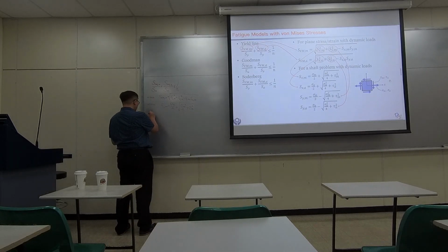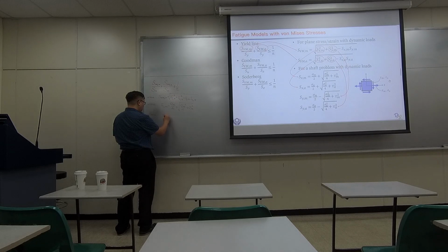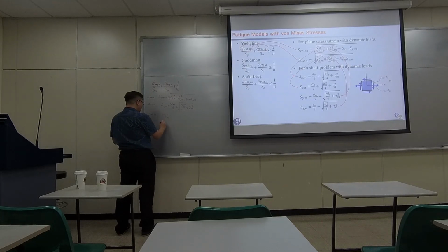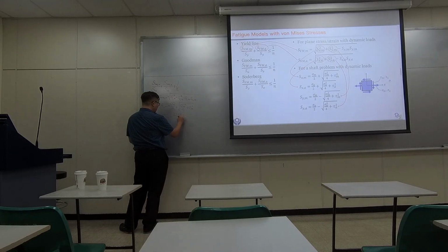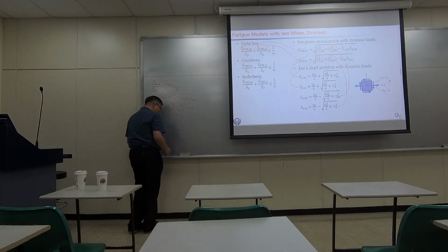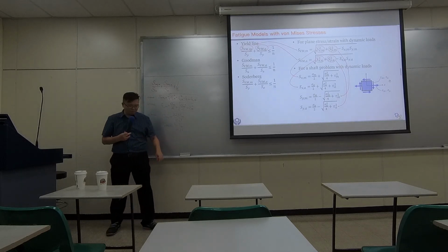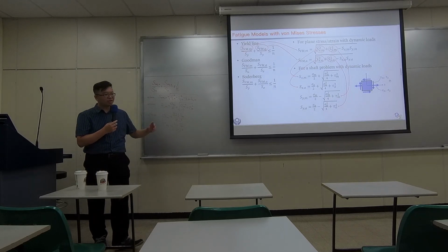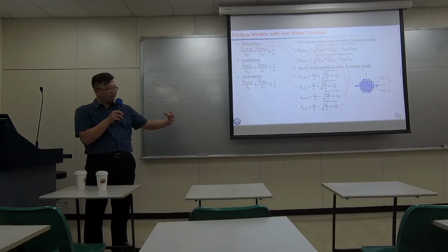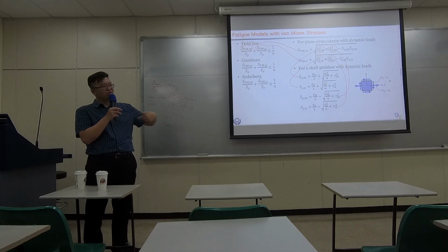Also, another where, how about sigma mean and tau mean? Basically they can be computed by 32 moment mean over pi d cube, and 16 torque mean over pi d cube. So in fact, what you usually know is the moment and torque. So here comes the situation. What if you have a shaft that is always spinning?